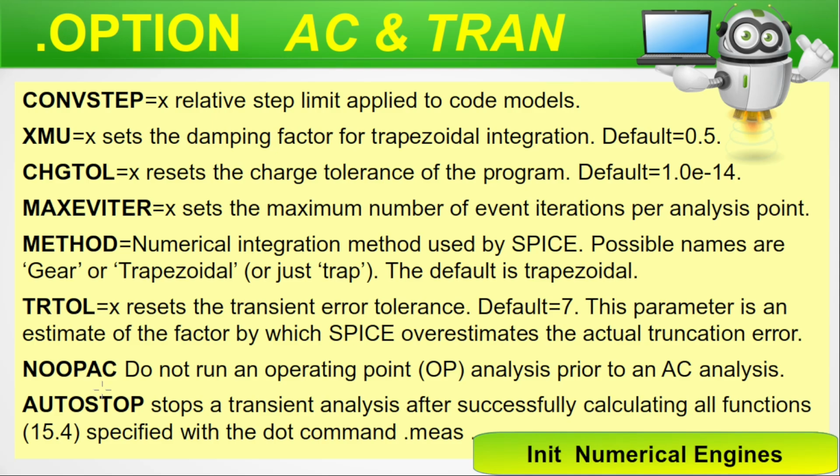In SPICE, what is the AC simulation? We have a periodic waveform as an input, the input vector. And what is transient? Where the output is with time. That means on the x-axis it will be time and on the y-axis it will be the waveform. So this way we deal with the AC and the transient. AC could be another thing: a circuit which has started oscillating can output an AC. That is another option, the AC analysis. We are all done with this slide, so let's move on to the next slide.